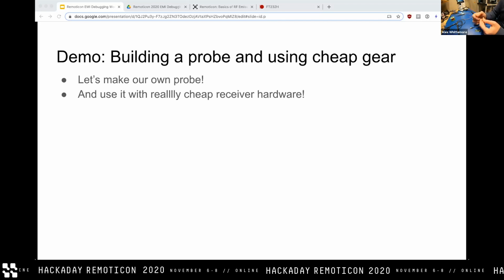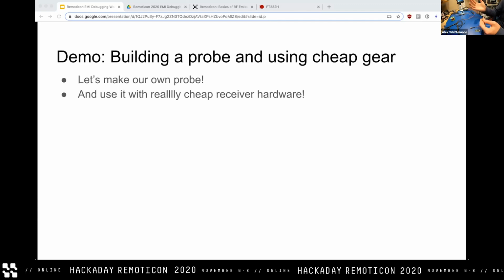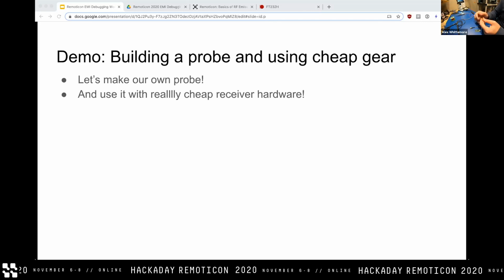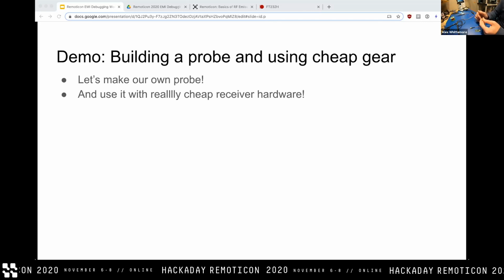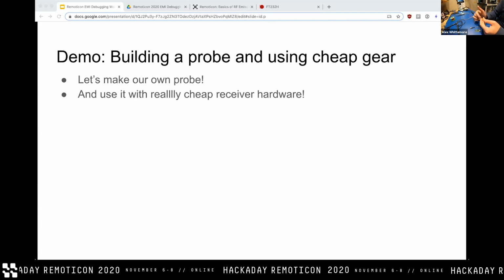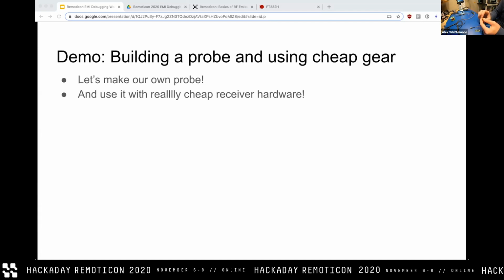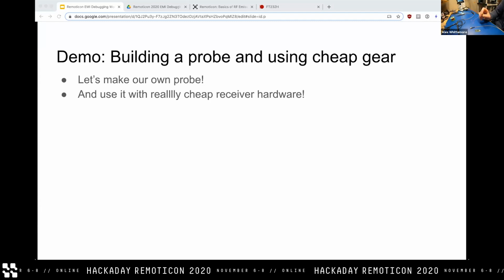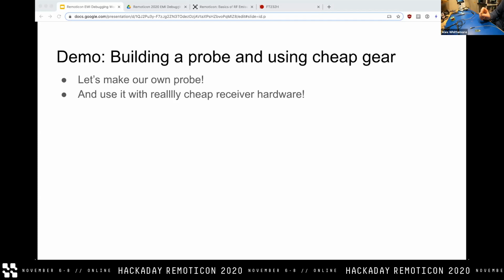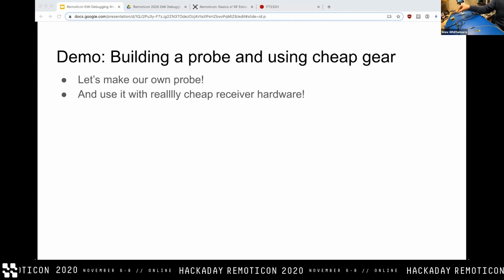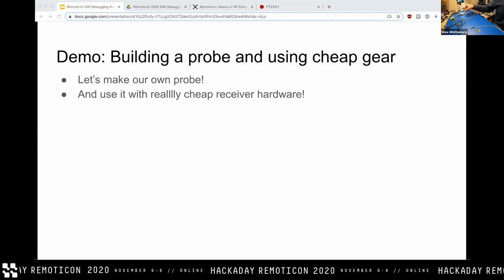And then the second half of this is, I think these pretty much just don't really require shielding to be useful, simply because they're like electrical short circuits at DC. So, you know, this will have terrible rejection in an RF sense, but also terrible sensitivity to electric fields. So we're basically just relying on the terrible sensitivity to E fields of a probe that just has a short circuit to ground effectively, and measuring primarily magnetic field instead.